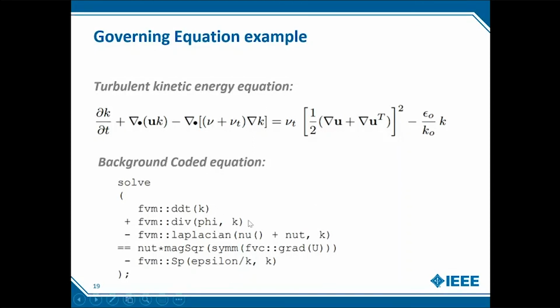So now if I want to solve a steady state analysis, I'll just go to the source code and remove this term. I'll just delete it. That's it. That's about it, and I'm getting a steady state equation, a steady state solver.